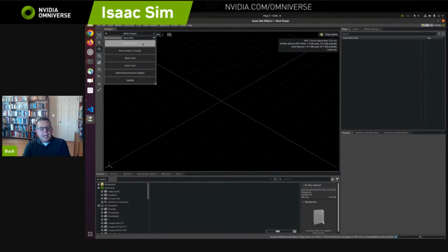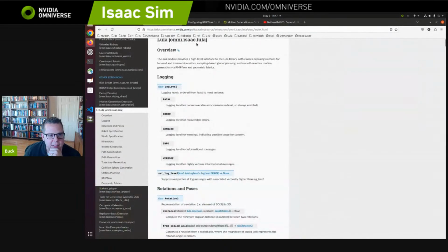If you have a robot and it's not doing what you expect, there are a couple possibilities. One is that you do have to tweak the RMP flow config file to get better behavior. But another might be that the simulated robot isn't following the trajectory that's being produced by RMP flow. And if that's the case, there are a couple tips for debugging in the RMP flow tutorial, which I can bring up since this is taking a long time.